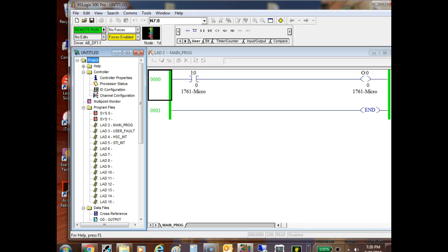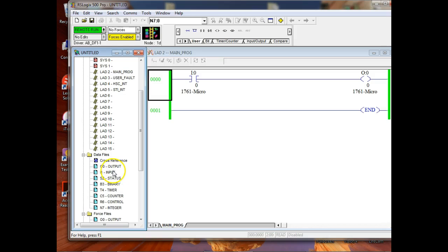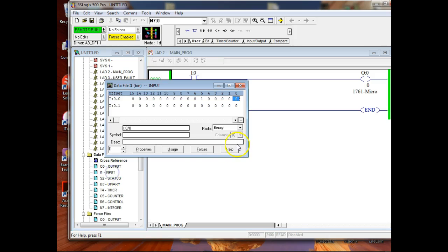Now if I come over here and look at the status of my inputs, this is what they were showing. So here's my inputs. I'm going to press that button right there. Can y'all see what it went to? 1. Now it's a what? 0. If I go down the next line, it doesn't make any difference. There's nothing hooked up to it. So this is what we're doing. We're taking an input and converting it over to a digital quantity.